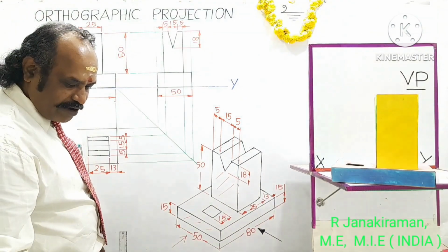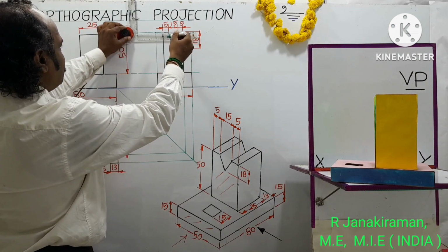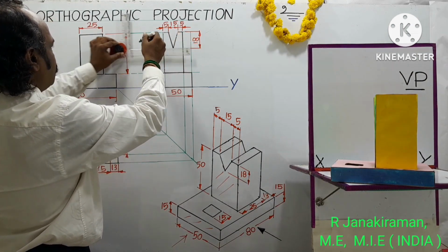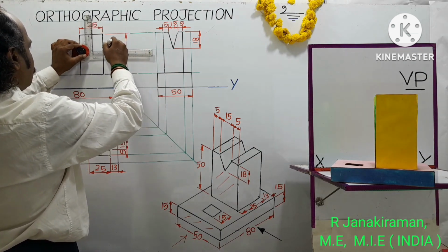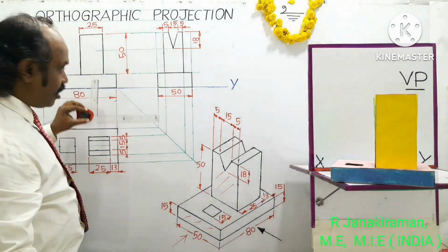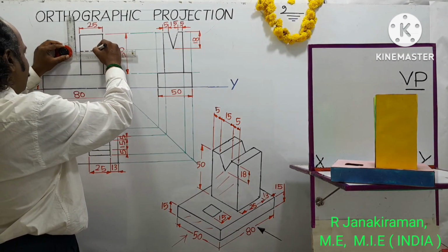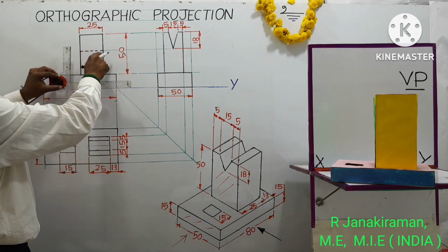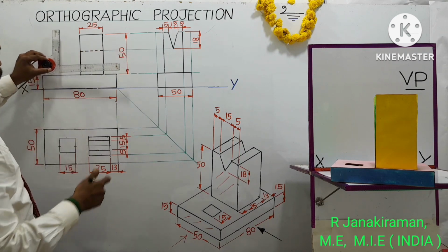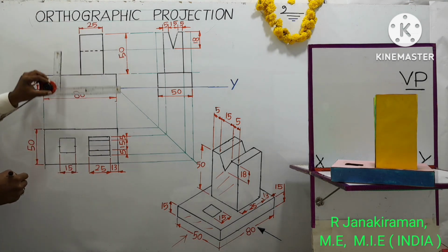Draw a horizontal projector from the previously drawn side view using a 2H pencil. So this is the passage. There you draw a dashed line. Something is passing inside, not seen in the front view, but it is available. It is represented by a dashed line, hidden broken line or discontinuous line like this. Usually a discontinuous line will not be dimensioned. That you have to understand.